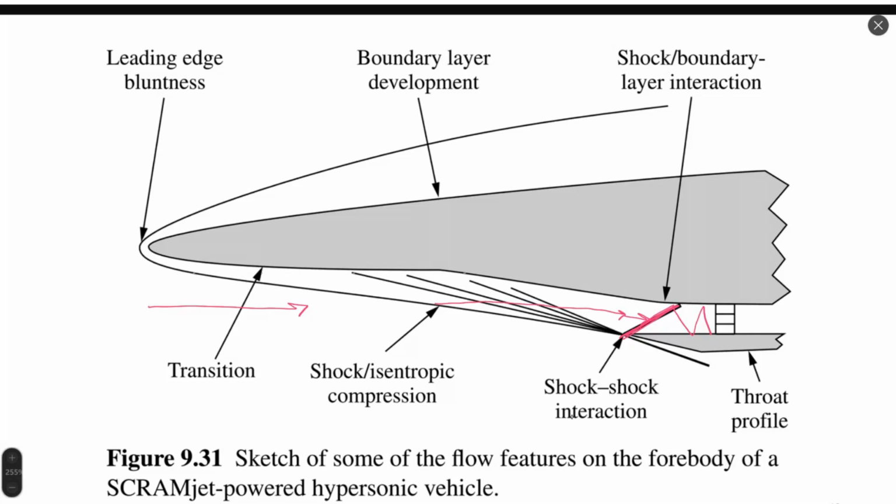This is why the lower edge of the diffuser is not parallel to the flow direction entering the diffuser. This is why, even when we have low supersonic velocity entering the diffuser, we start to have a series of shock waves reflected from the walls. Such a reflected shock wave is caused by the non-symmetrical flow between the diffuser wall and the flow which enters inside.